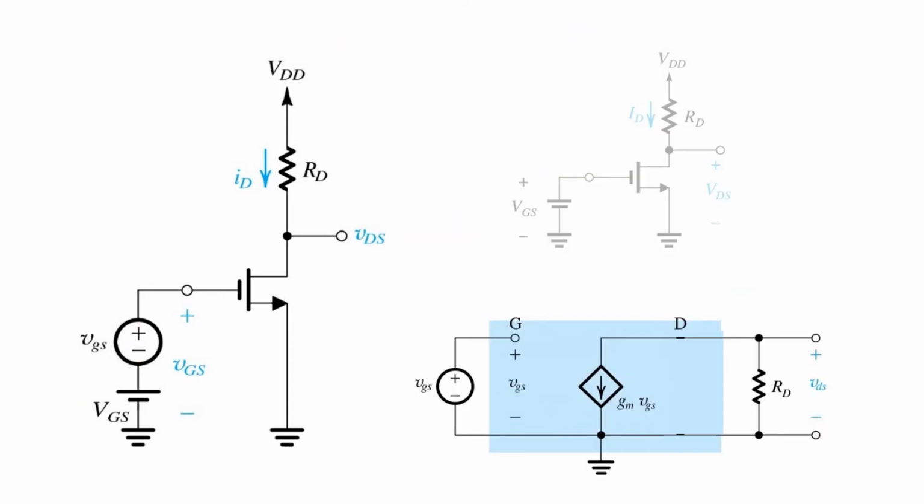So having done that, we can now move on to the second step, which is to linearize the circuit. And by this I mean essentially take the tangent to the IV characteristic at the operating point and use that tangent as a linear approximation that relates the small signal terms, lowercase VGS, lowercase ID. It's riding on top of the DC operating point, uppercase ID, and so on.